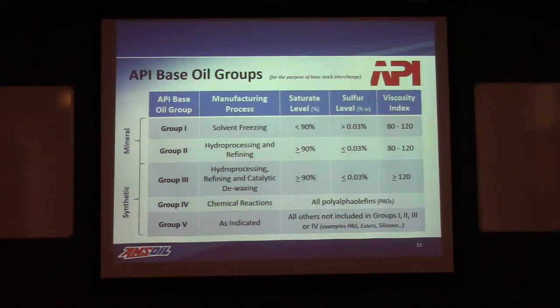They do have issues with uniformity and molecular structure. They do have contaminants like we talked about, and they really don't have the functionality over the broad temperature ranges. We talked about that when I brought up the example of jet engines. You know, they just couldn't handle it. Group 3 actually starts out as a mineral oil.